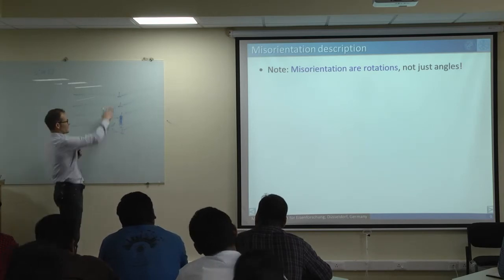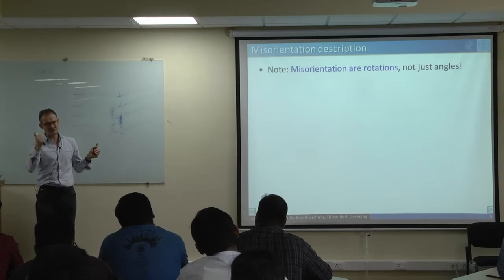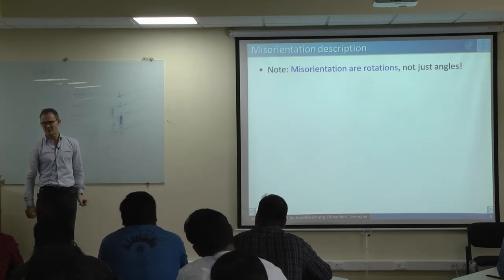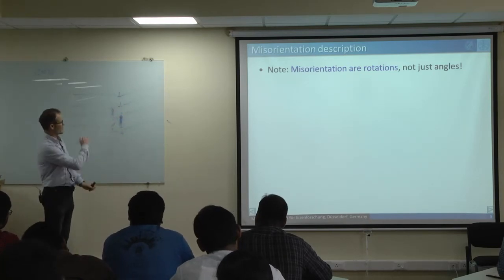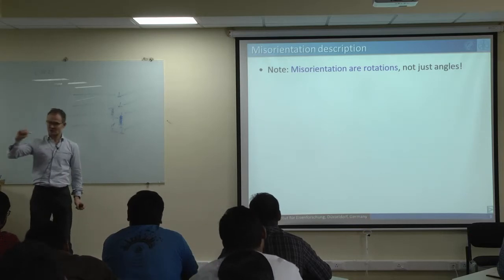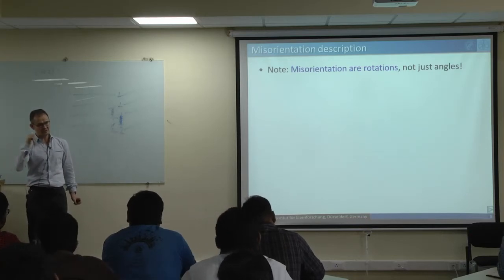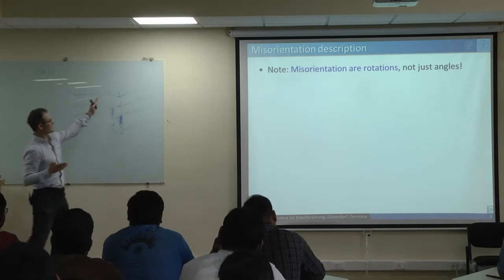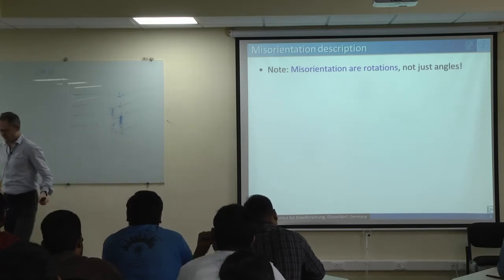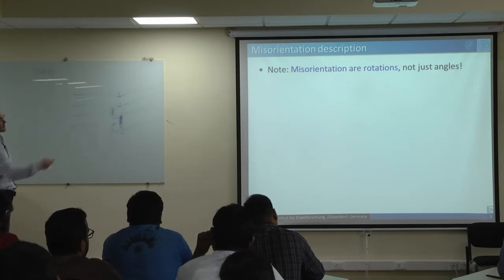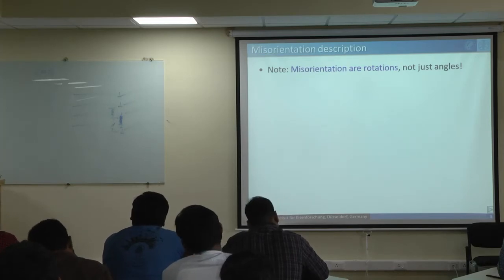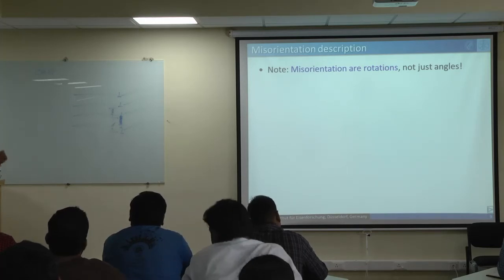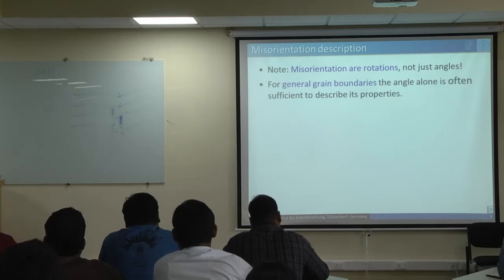Sometimes you still find some regularities in there, but you can consider that the grain boundary is kind of amorphous, a random arrangement of dislocations, particularly when you start deforming it. This is visible in the energy of the boundary, but even more characteristic is the structure of the boundary. There, the misorientation just as a rotation is about sufficient, not fully, because you still have to distinguish between tilt and twist boundaries. We'll come to that in a second.